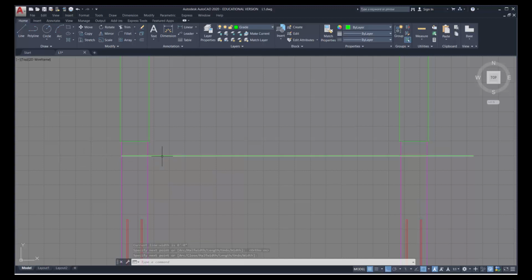Now I want to extend the other side as well. Well, the easiest way to do it is, because this is a symbol, a drawing element which simply represents an object as opposed to a precision drawn item, I'm going to click on the line and then click on the node and move it to the left. And what that allows me to do is extend this without having a boundary edge, because it really doesn't matter how far we extend that beyond the edge. Press Escape.